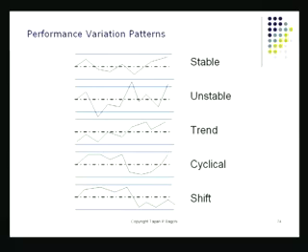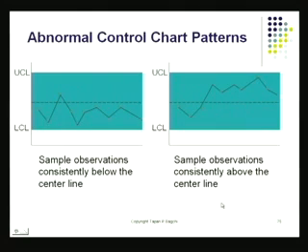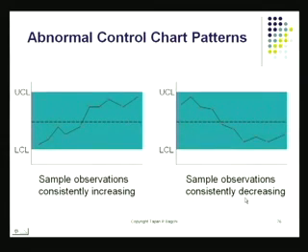Now, if you watch the height of the chair at different hours in this studio, you'll find that the height is changing like this. It is going up and down like this. And that is exactly a shift in the average. That's the lowest pattern. This is also something we'd like to see. So the same kind of abnormal behavior is there. You see the chart going from one side of the midpoint to the other side of the midpoint. This is also a signal that something is happening with the process.